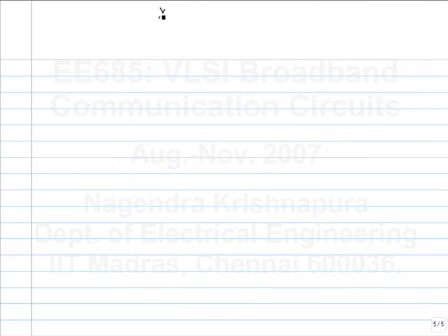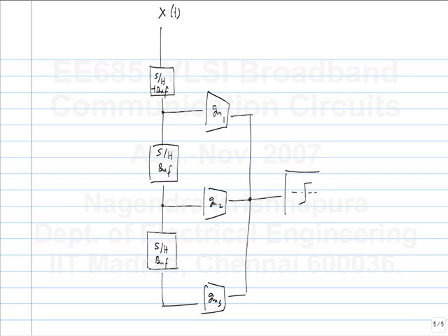So let's say my continuous time input was here. I have sample and hold. Instead of drawing two blocks, I will show the buffer also inside this. So this is my data slicer. I get y hat and y, and I can also determine y minus y hat. I don't imply that you subtract y hat from y directly like this. There are other ways of doing it which we have already studied. That is, you subtract a fixed quantity from y and slice that. This is E.